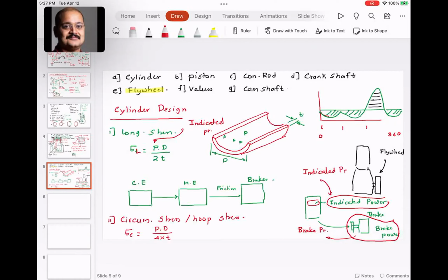Correct. And that is the reason why the aluminum soda can cracks vertically. If you look at both these equations, sigma L and sigma C, the circumferential stress, the pressure is the same and the diameter is the same, but the longitudinal stress is significantly higher. That shears or cracks the shell, and that is how the soda can fails.